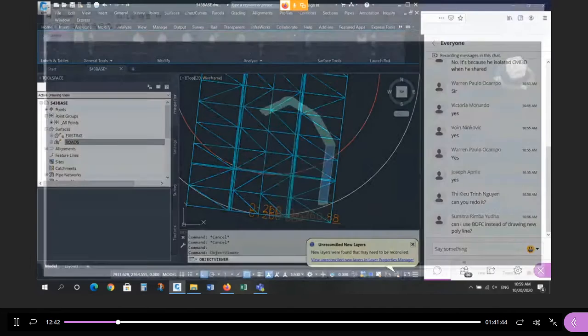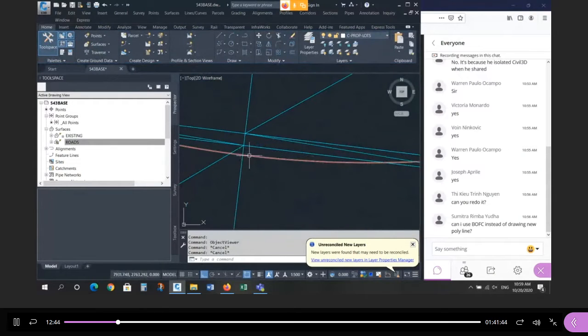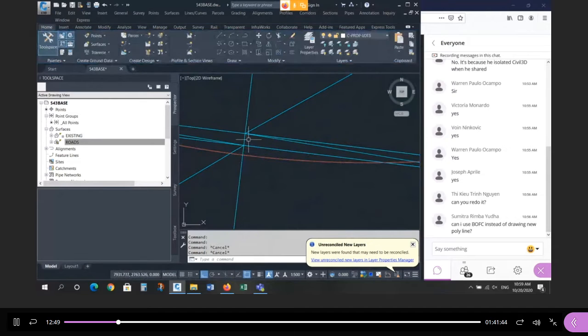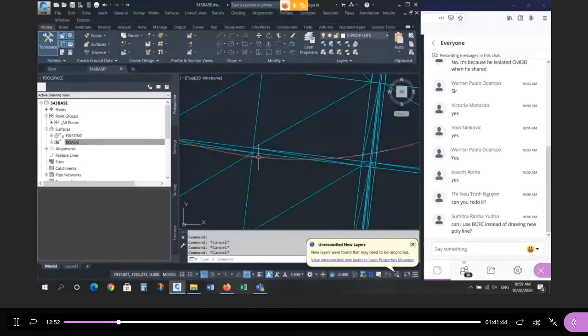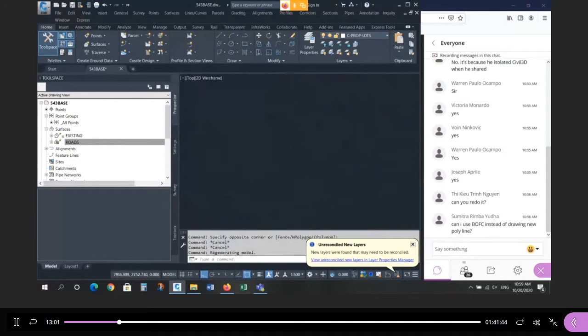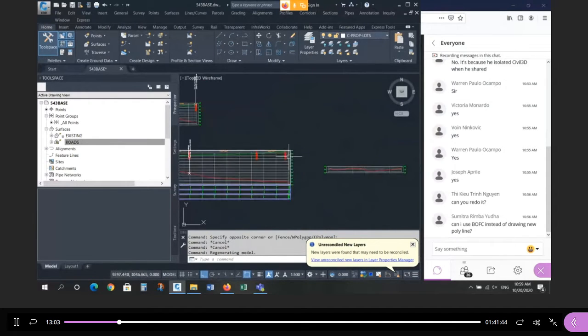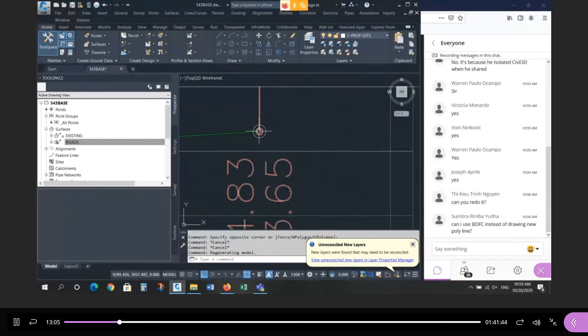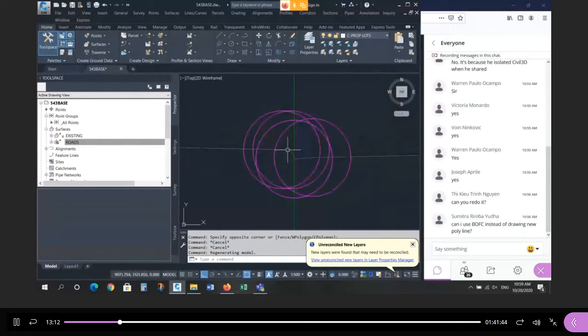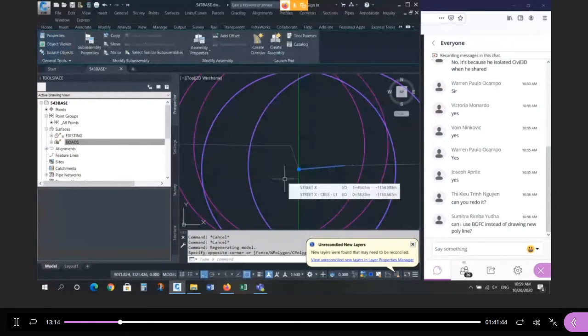So I want to know the elevation in the gutter, right where the center line crosses this surface. And it's going to be wrong right now because if you remember, we didn't design to the gutter. We designed all the way to the edge of asphalt. So there's a piece missing. So there's a surface there, but it's not representative. So I have to go back to my profile. Okay, I'm going to go back to my profile, and 0.3 meters away, I want to put in my gutter. Okay, and remember the slope of the gutter? Anybody remember the slope of this piece here?